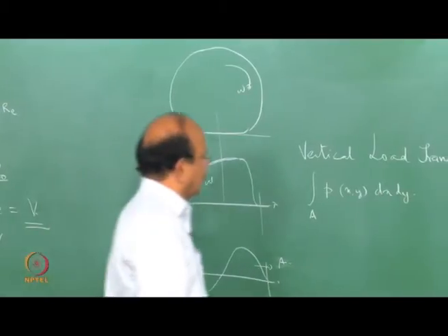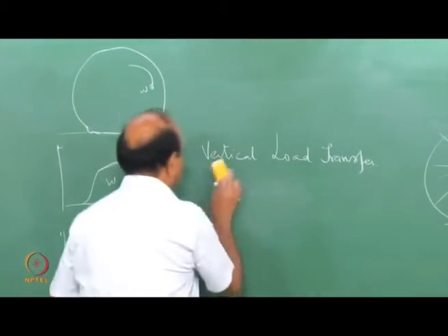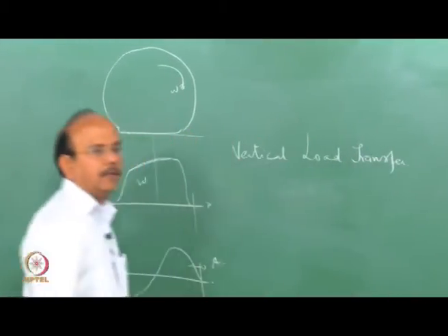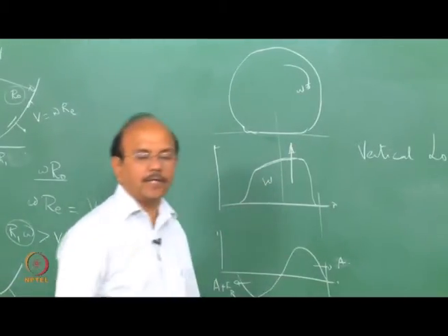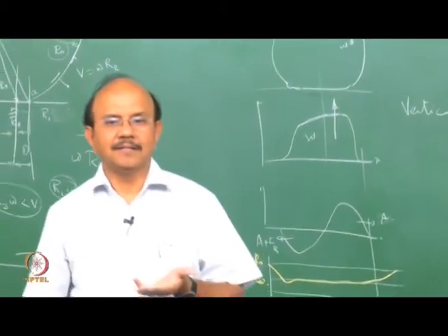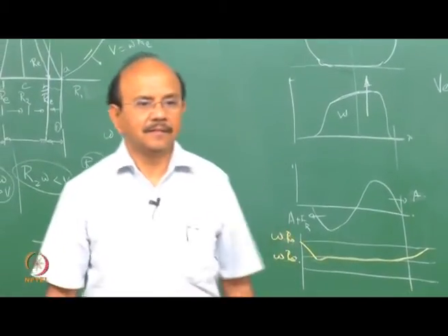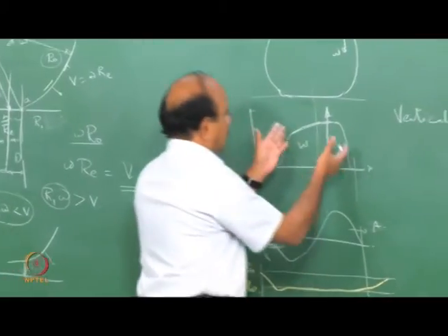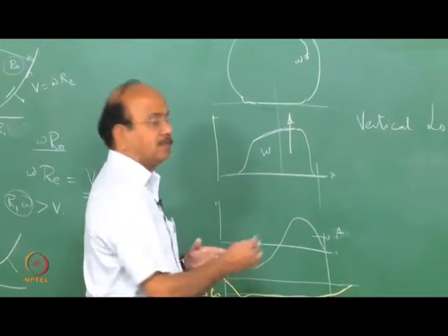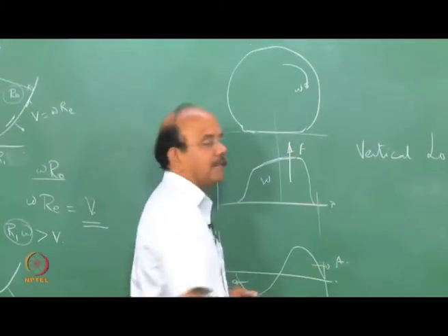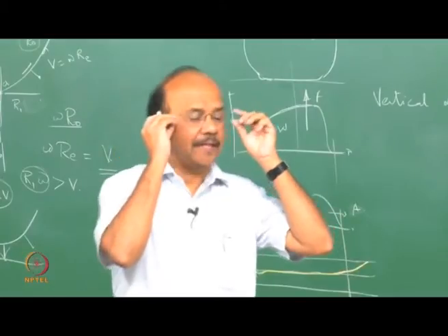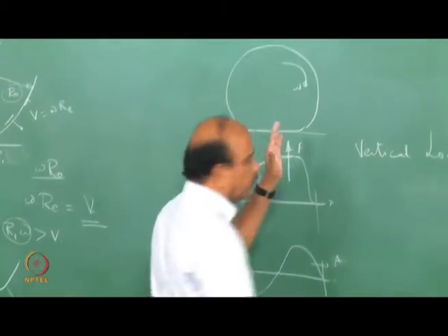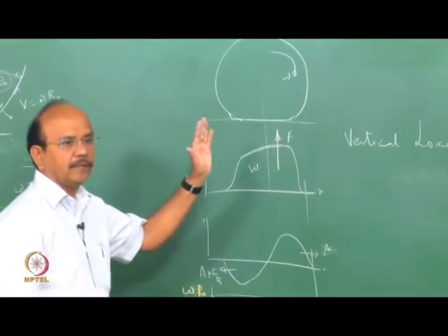As we had seen earlier, this is not symmetric for a rolling tire, with the result that the unsymmetric distribution results in a force which is responsible for rolling resistance. We said that the unsymmetric distribution is due to the viscoelastic properties of the tire.